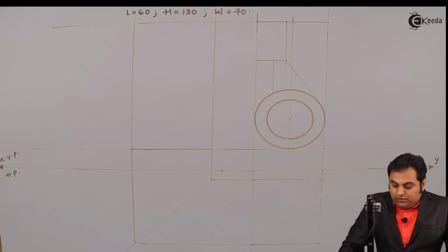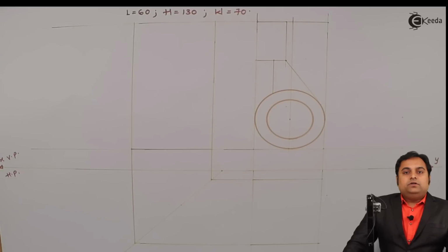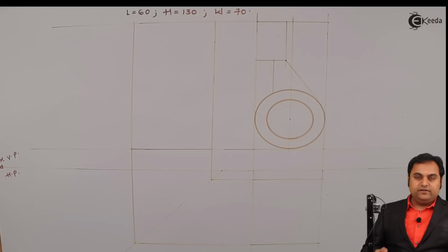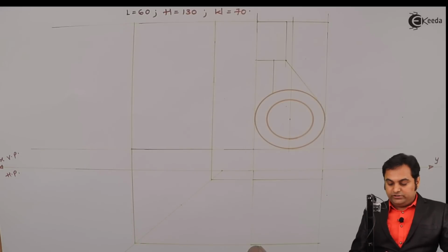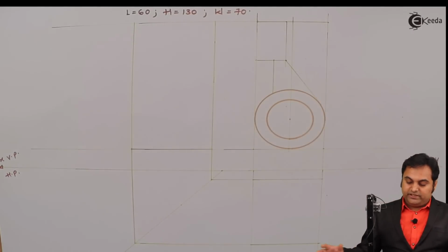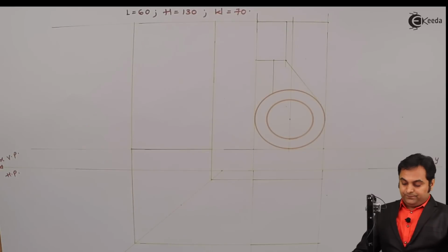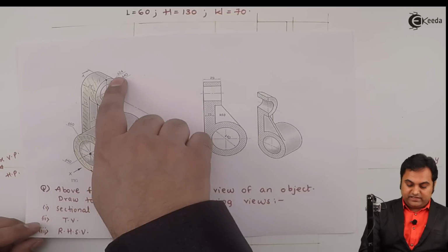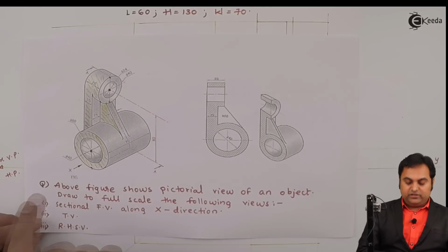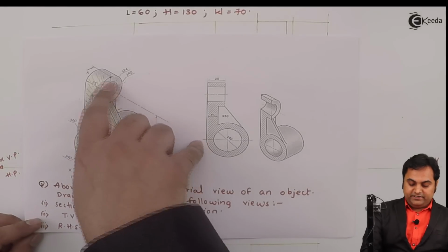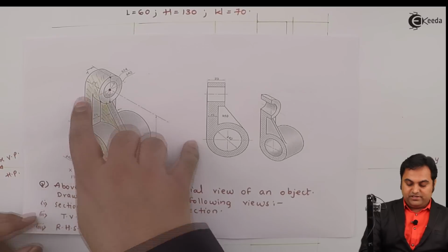Now when we are drawing sectional orthographic projections, we have to draw it plane first, that is without taking any of the sections. So here I have drawn it plane without taking the section. Next, inside this surface there is a circle having diameter 24, which again will not be visible from X direction, so it will be hidden throughout this 25 mm length.